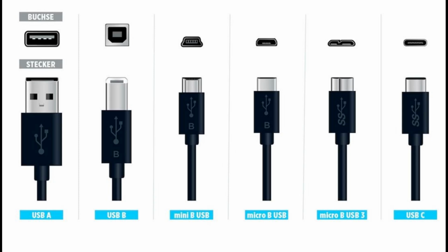The USB4 specification was released on August 29, 2019 by the USB Implementers Forum. The USB4 2.0 specification was released on September 1, 2022 by the USB Implementers Forum. USB4 is based on the Thunderbolt 3 protocol. It supports 40 Gbps throughput, is compatible with Thunderbolt 3, and backward compatible with USB 3.2 and USB 2.0. The architecture defines a method to share a single high-speed link with multiple end device types dynamically that best serves the transfer of data by type and application.